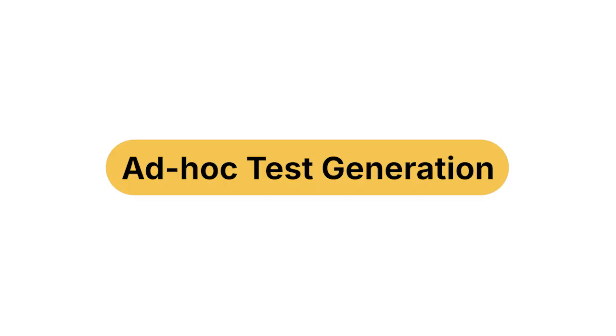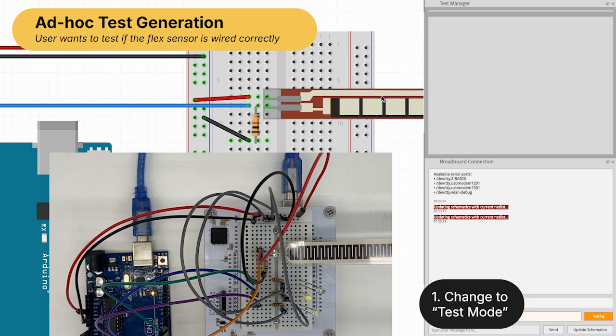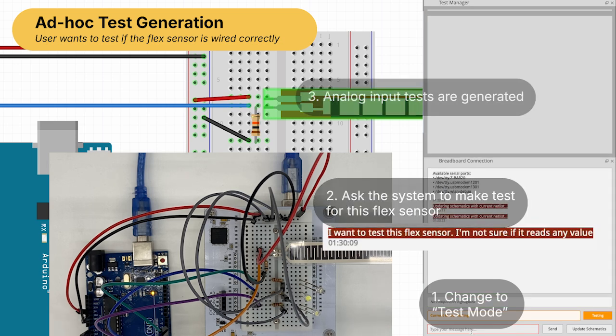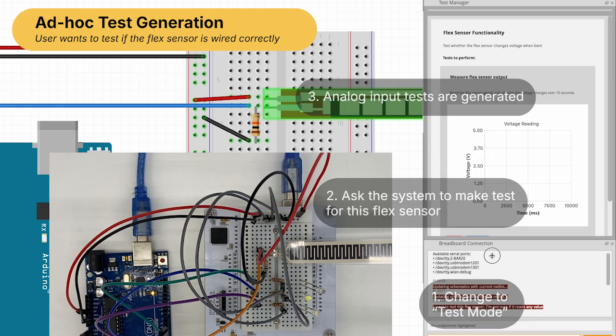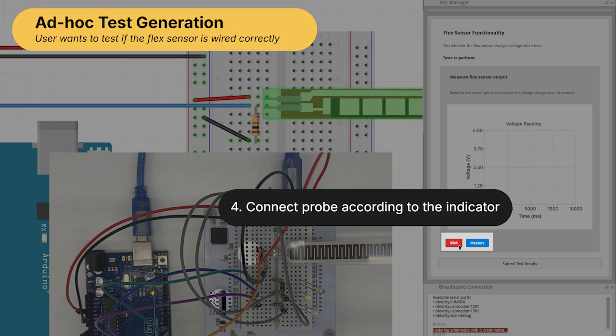Wireway can also generate tests to verify the current circuit configuration. Here, the user wanted to test the new flex sensor circuit. They clicked the mode button to switch to test mode, highlighted the flex sensor subcircuit, and then asked the system to make a test. The system generated an analog voltage read to visualize the input of the flex sensor. It highlights where the probe should be connected.